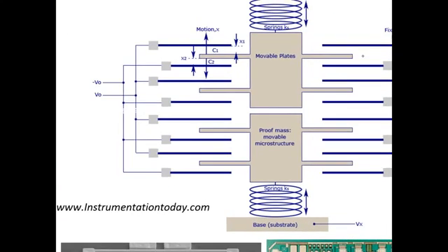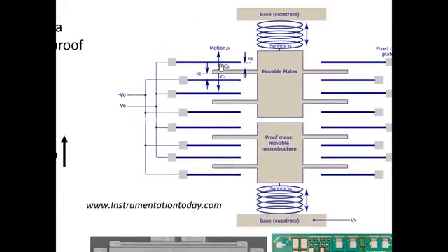There are two aspects of that I should clarify. One is the differential sensing aspect of it. So when this is moving up, this capacitance is decreasing and this one's increasing. That's the differential part of it. The reason they have multiple legs on here is to increase the effective capacitance. These types of sensors become more sensitive the more capacitance you have. By putting another leg here, they have a second capacitor, so they get a larger capacitance change when this plate moves. That makes the system more sensitive.